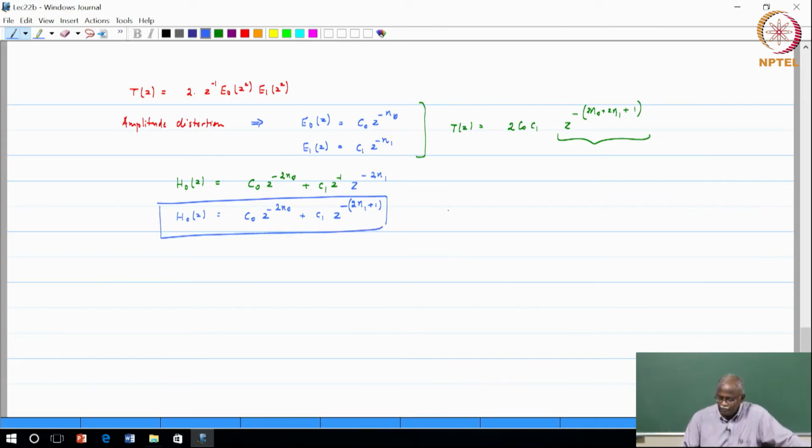So basically an impulse response that looks like some combination of delays, and you cannot get very good filters with just a 2-tap filter, you cannot get very good attenuation. So yes, this is okay, but this is a very restrictive case, this is not going to really satisfy.